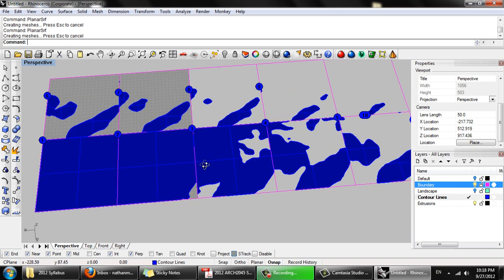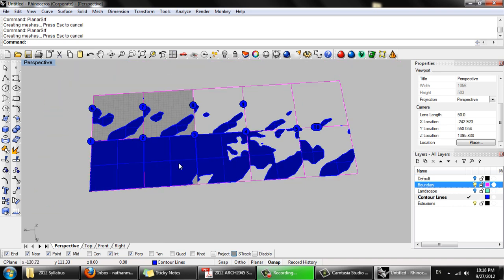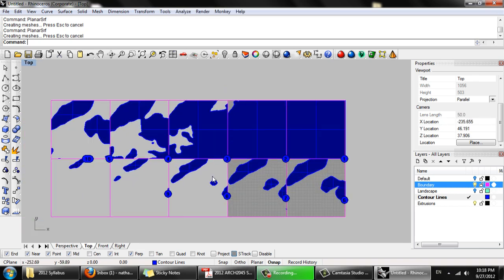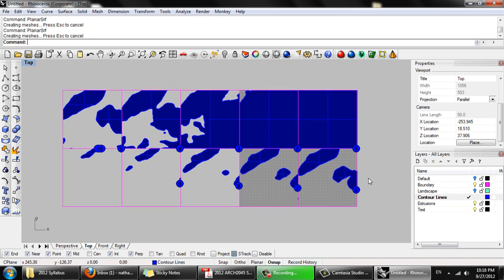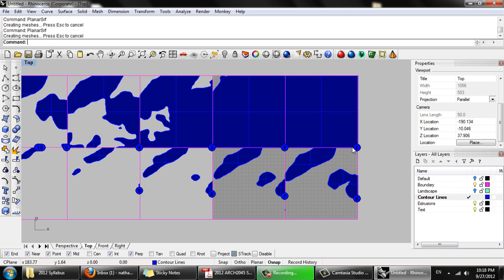Okay, so if we start moving this around, we're going to perhaps lose track of what's on which layer. So let's go into top view and try to be a little bit more precise. When we laser cut, we can also etch on a separate layer. So we can specify a number, and that can be etched on top of the cut geometry. So let's create a new layer. Call it text. Because these text dots won't actually be cut, this is just for our reference. And then we can create a text object on this layer.